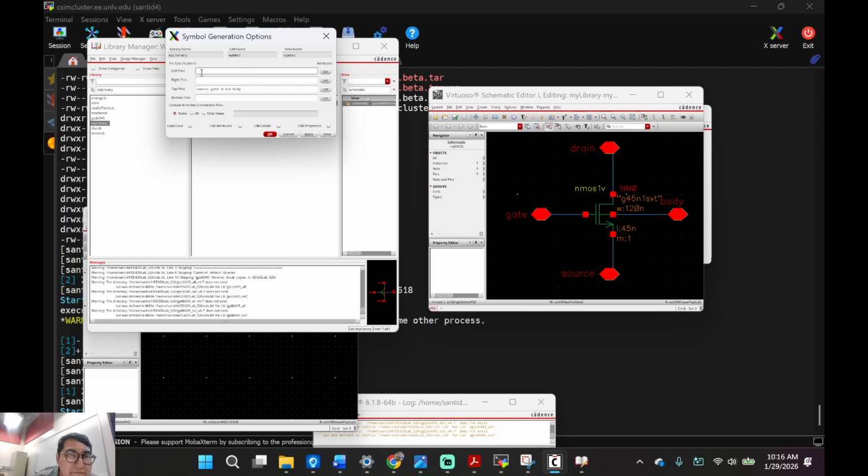And then it says left pin, right pin, top pin, bottom pin. So I'm going to put the left pin as my gate. So I can delete that there. Put gate. Right pin, I'm going to put body. Oh, I can't even type body. Oh, come on. This is what I'm talking about with Cadence being funny. By the way, please be saving this because there's a chance Cadence can crash. I think...